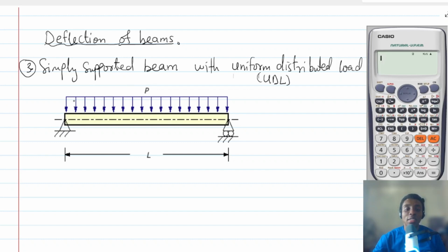So you are going to assume that if I take each portion, there is this load. Okay, therefore the average load on the entire section which I will get is going to be in the form of a rectangle. All right, so this load is occupying the form of a rectangle. And what's the area under the rectangle? That is the length by the breadth. So we are going to assume that the length is the L that we have here, and the breadth is the load, which is P that is coming. So it's going to be P multiplied by L.